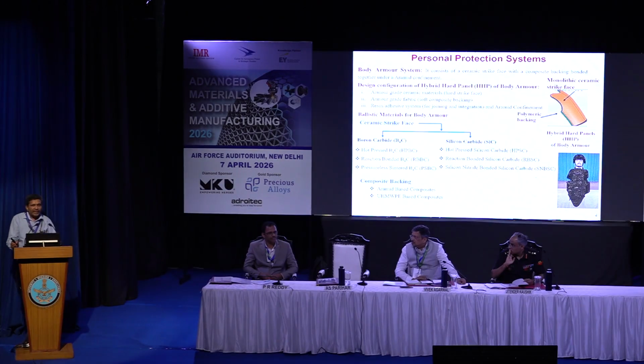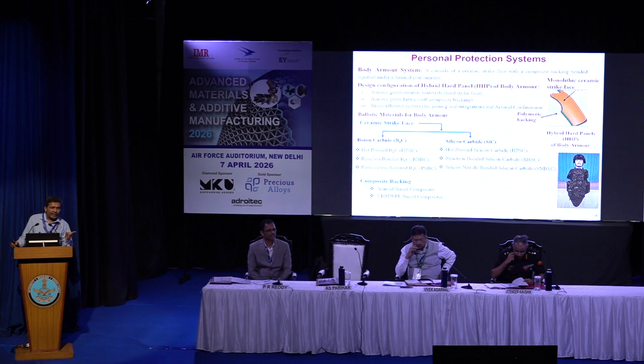The areal density should not be more than 40 kg per meter square. So we have both solutions: with the boron carbide, we have the areal density in the range of 38 to 39 kg per meter square. Again, the boron carbide has three types: 2.5 density, 2.6 density, and 2.9 density using the TiB2.